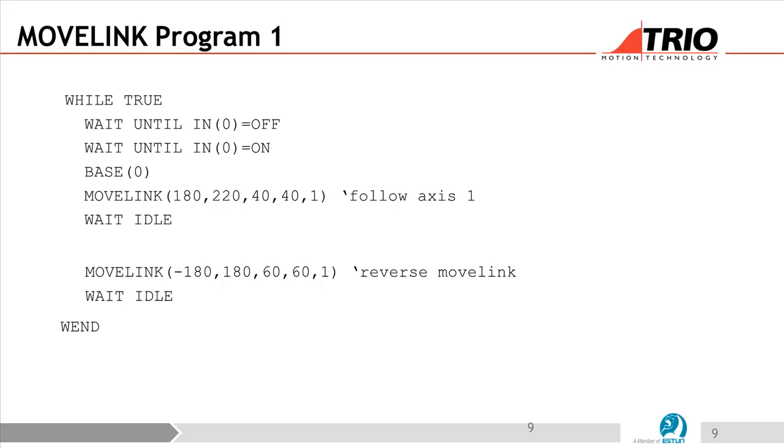So in that particular case, it's actually going at a higher ratio. Or we can use the MOVEABS 0. Yeah, exactly. So the advantage of a reverse move link is that it gets softer as the machine slows down. If you use a MOVEABS 0, yes, it can be more efficient, but it's always going back at the maximum speed. Okay. But you definitely always go to 0 every time. So yeah, there are advantages both ways.